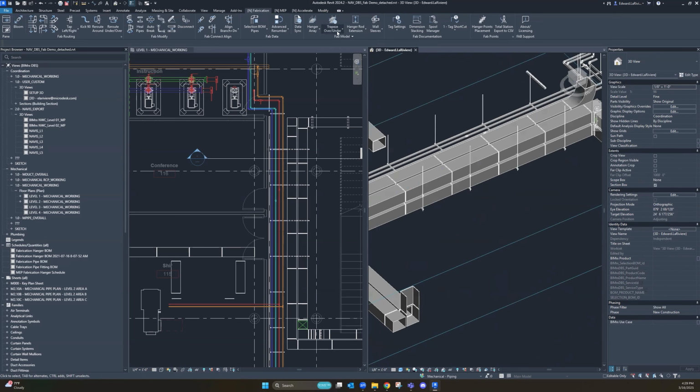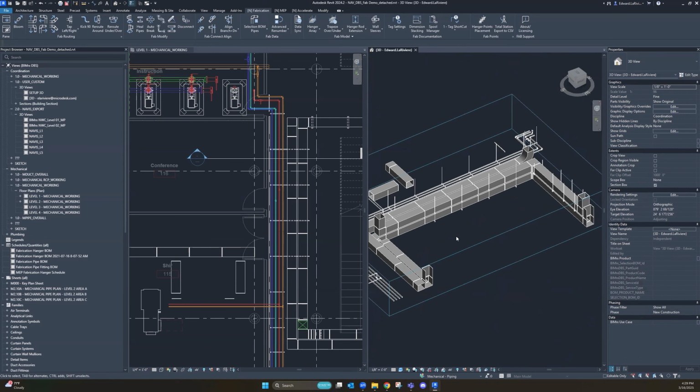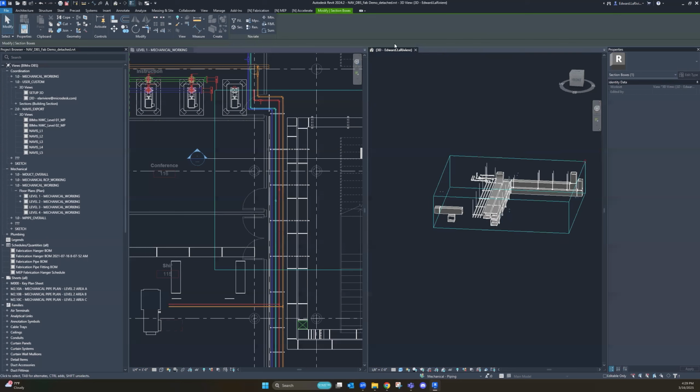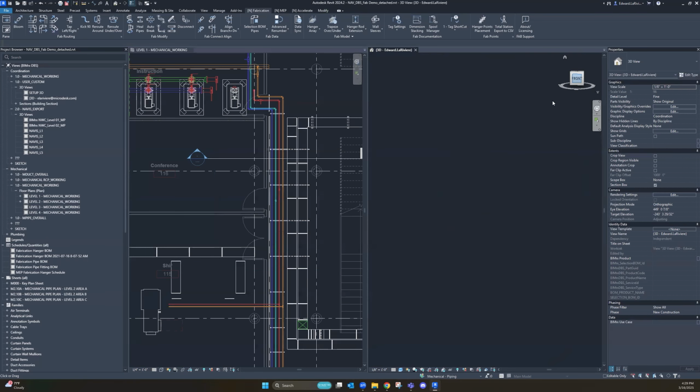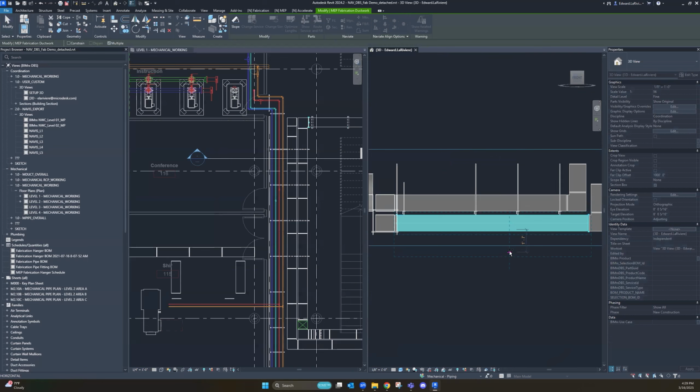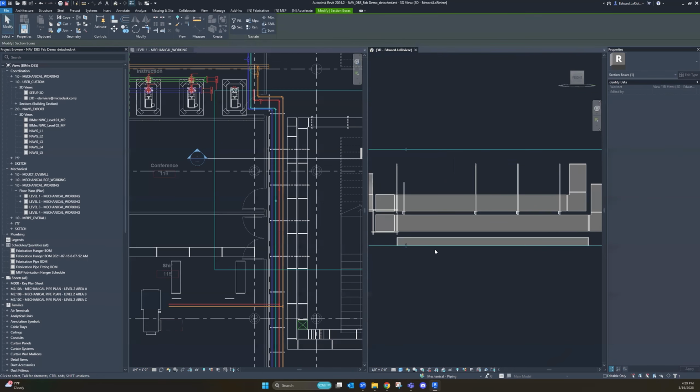So what we're going to find is Trapeze Over Under is for adding a hanger that hangs off of a hanger. Now let's do something a little bit more interesting with our multi-rack tool. Jumping over this way, I'm actually going to give us a 3rd tier to work with to make this really interesting.